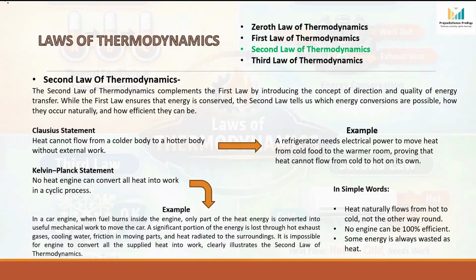Electric power runs the compressor, and the compressor circulates the refrigerant to carry heat out of the refrigerator and reject it into the room. So instead of sending cold air inside, the system is actually pumping heat outside. This is a perfect real-life example of the second law of thermodynamics, which tells us that to move heat from cold to hot, external work is always required.